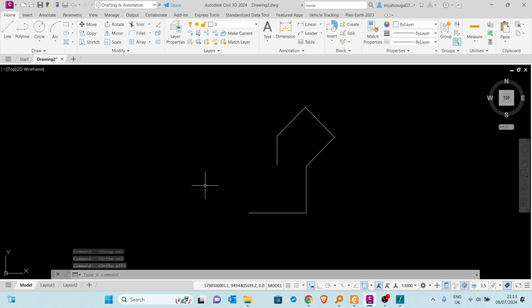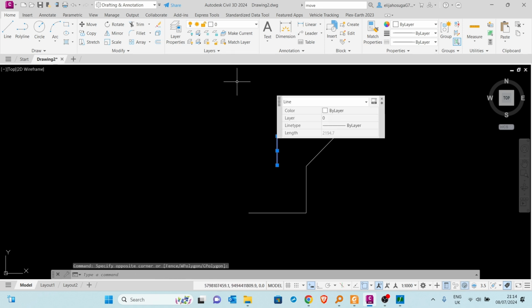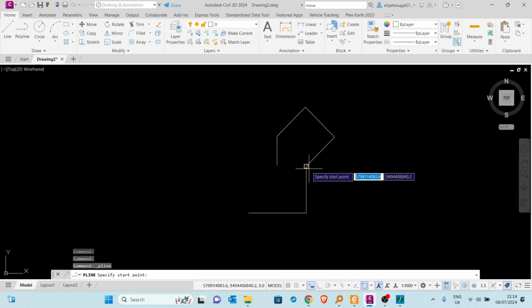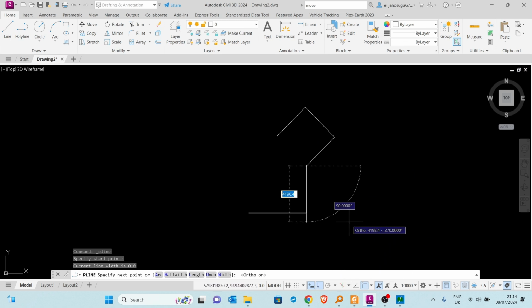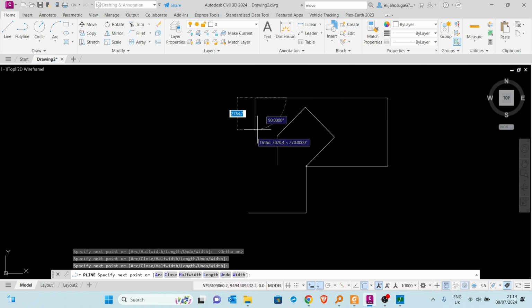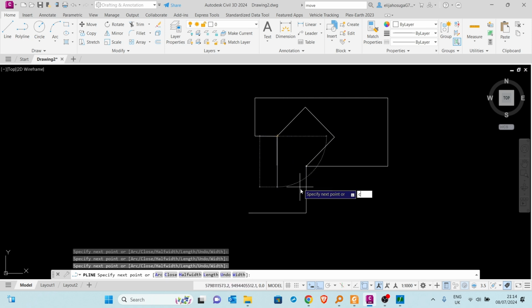That is the line command. So there's usually a difference between a line and a polyline. As you can see, in the line command, we were drawing a line and it was giving us a segment. But if you were to draw a polyline, for example, snap, click F8, I go, click there, go, I go there, then let's say I click on C to close.